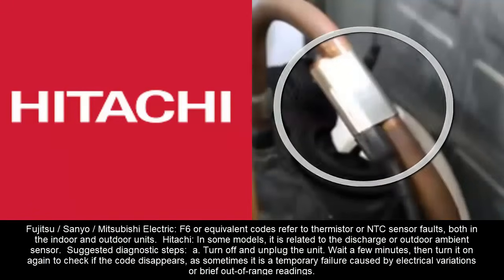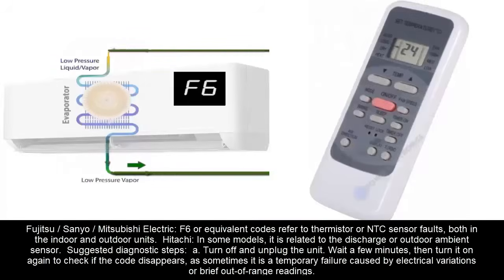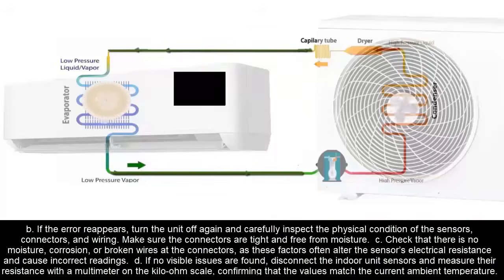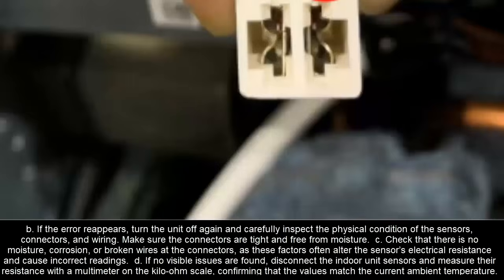Suggested diagnostic steps. A. Turn off and unplug the unit. Wait a few minutes, then turn it on again to check if the error disappears, as sometimes it is a temporary failure caused by electrical variations or brief out-of-range readings. B. If the error reappears, turn the unit off again and carefully inspect the physical condition of the sensors, connectors, and wiring. Make sure the connectors are tight and free from moisture.